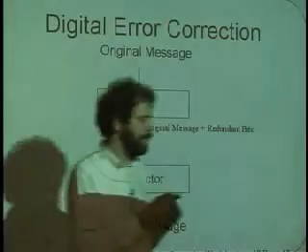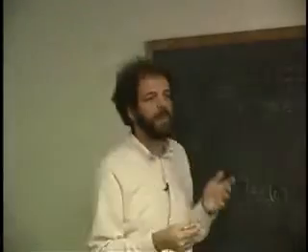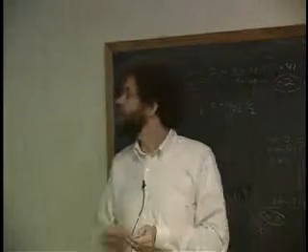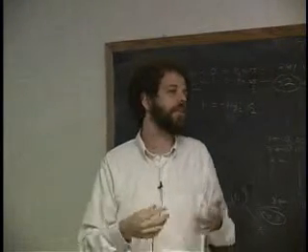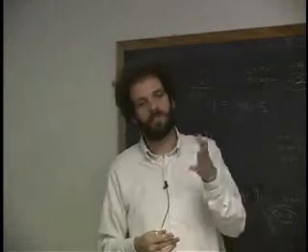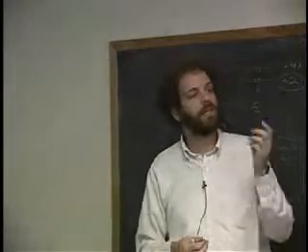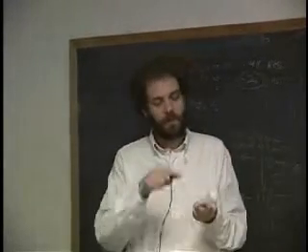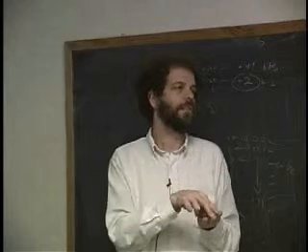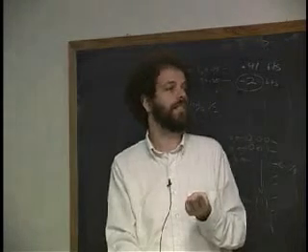And there's a whole science to how to design those two things. A very simple one you might want to think about is take every bit that you get in and replicate it. For every bit you get in, send 2 bits out. It turns out that's kind of an inefficient one, but what if for every bit you get in, you send 3 bits out? That way, if any one of them dies, you can look at the other two and just take a majority of every 3 bits to determine the 1 bit that gets out.